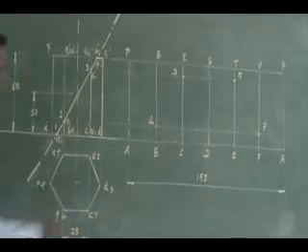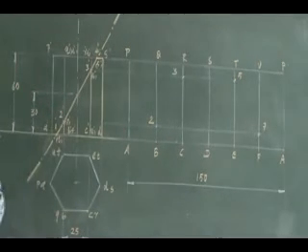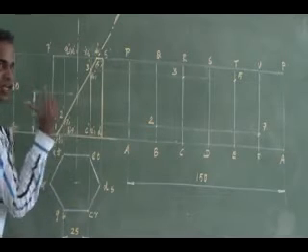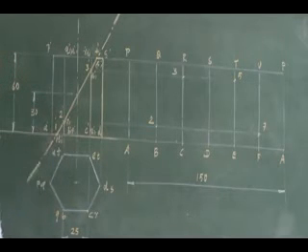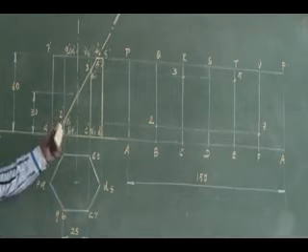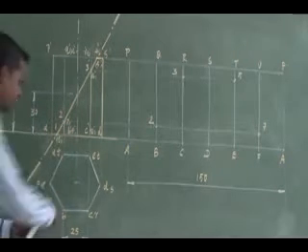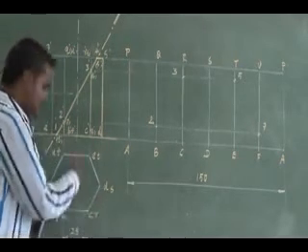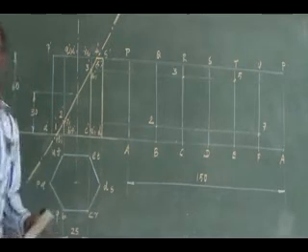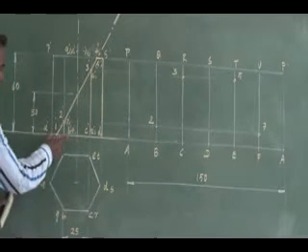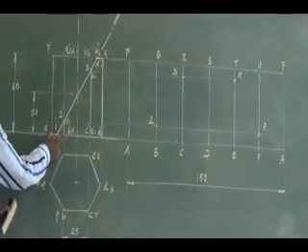Right? So how exactly can I transfer that location? This is a front view projection, so you don't know the exact location in the front view. What I can do is extend these cutting points to the top view. Here I have the exact length of the base sides. Here I don't have the exact length of the base side in my front view.